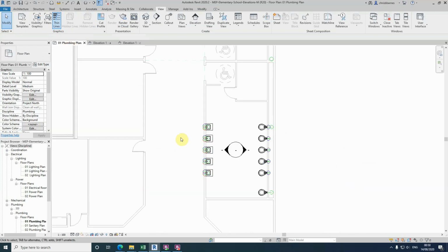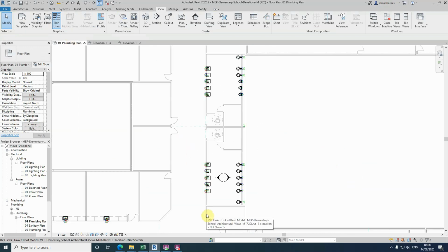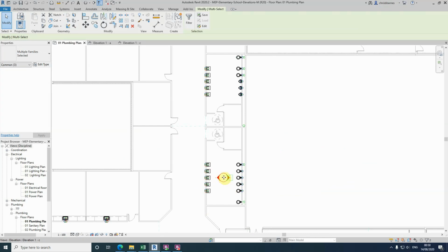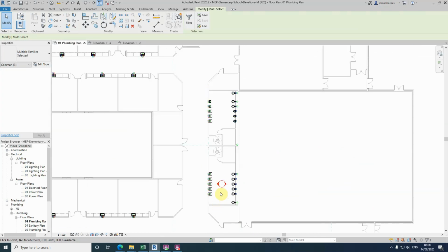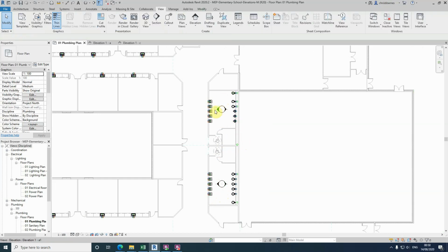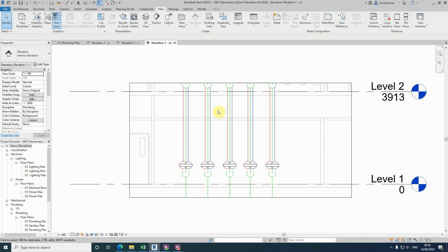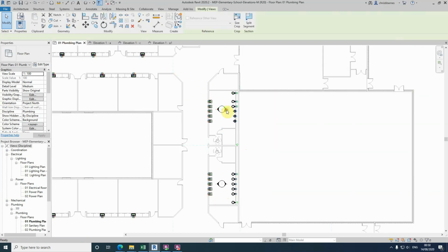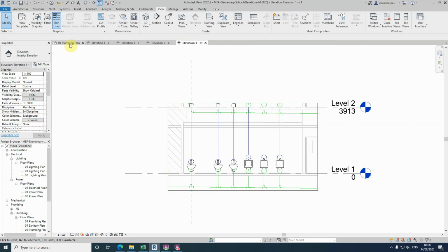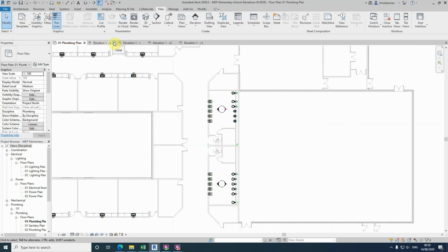Now we're going to go back to here. What we're going to do now is select the entire circle here, both arrows, and whilst we hold the control, we're going to drag this up to the next restroom and then let go of everything. What we've just done is copied it up, so we've both got exactly the same details. Like this. And as you can see, we've got elevation 1, A, C, A1 and C1.